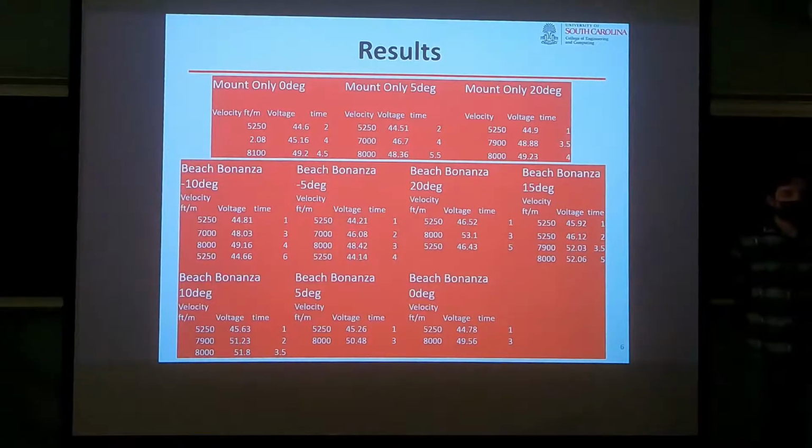Initially we thought the values of the voltages would jump up and down a lot, but it kind of didn't. You give it 2 to 2.5 minutes and it would get stable, maybe changing by 0.01 volts, which was still pretty nice. So at least with this load sensor, the vibrations were not as much of a hurdle. That kind of brings us to the point that the load sensor is not really sensitive or accurate, because if it were really accurate, it would jump up like crazy. But yeah.